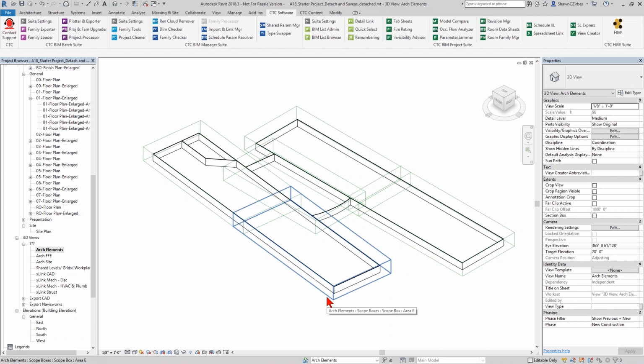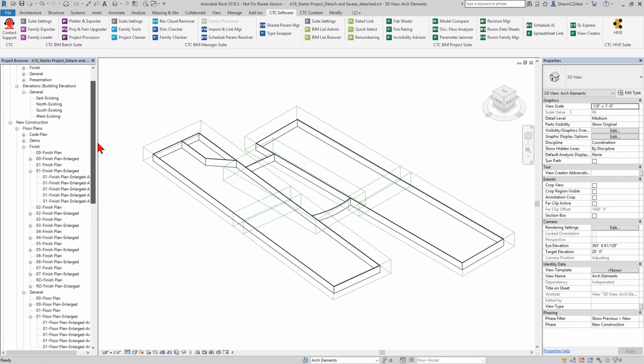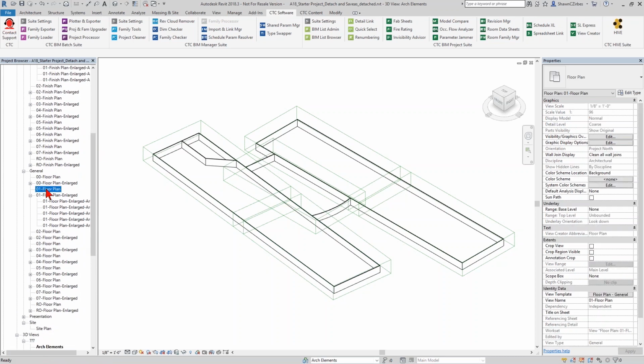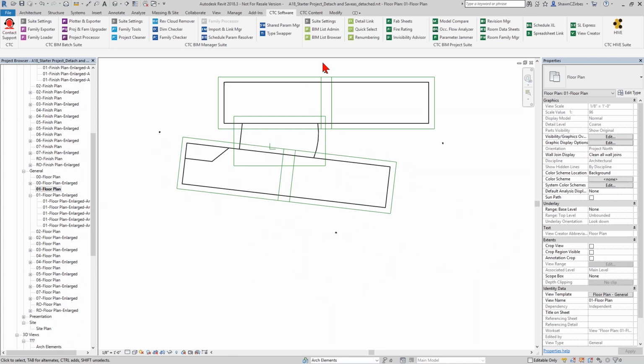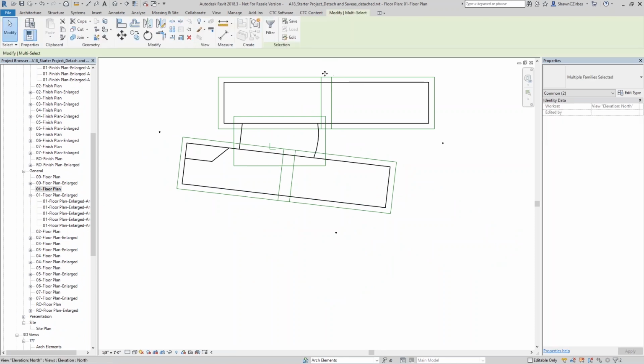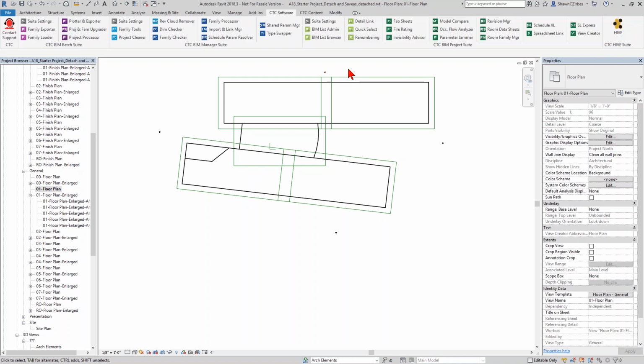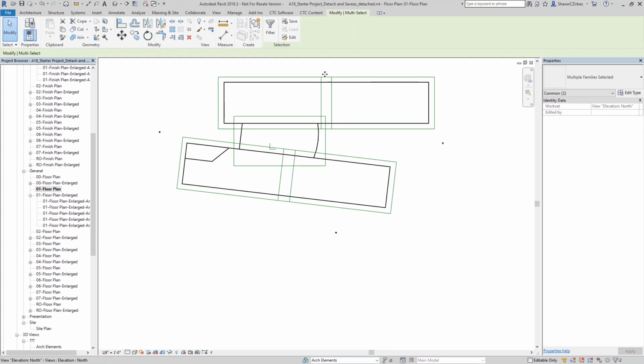I want to take a step back for a second. There was a question that I saw show up here. It said, how are elevation tags being placed when duplicating elevations? What it does, if I go back to one of my floor plans in my new construction view, is it effectively takes the exact elevation with a tag, copies it and pastes it in place, sets its name, and sets its phase. So it's not dropping a brand new elevation in and then setting all the properties. It's just copying and pasting exactly what's already there.